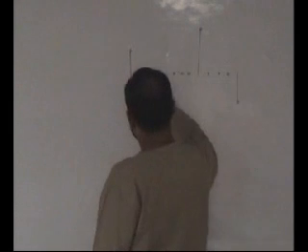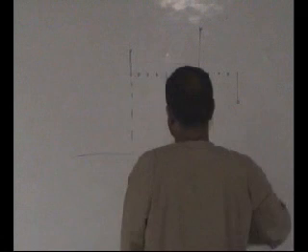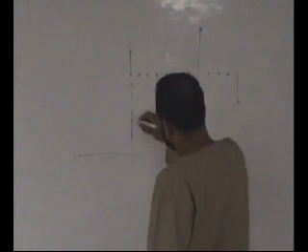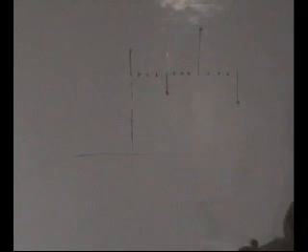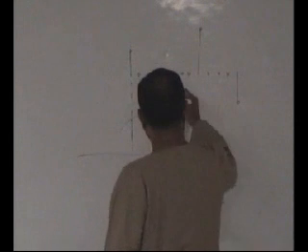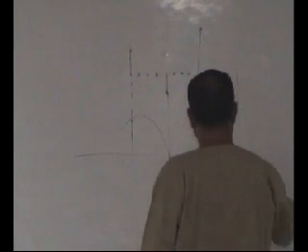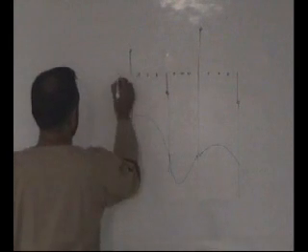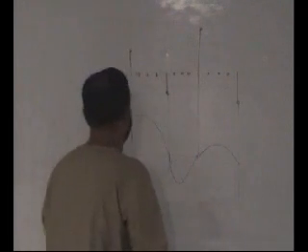Once you use the sinc, it will always pass through zeros after L samples, guaranteed. Okay, so the sinc will be something like this. This will pass through this 0, then this 0, then this 0, and similarly if you have something here, it will pass through this 0. So this is a sinc.